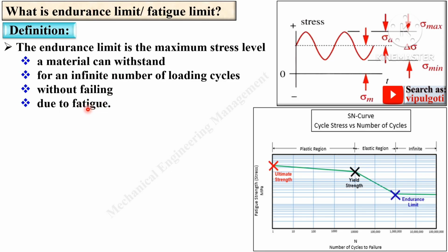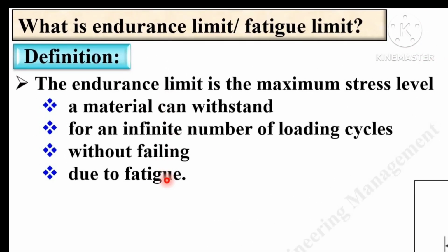Endurance limit is for the fatigue load only. So if there is a fatigue load, then the maximum stress level is known as endurance limit. Very simple definition. Point number one, the maximum stress level a material can withstand. Second, for an infinite number of loading cycles. Third, without failing due to the fatigue.